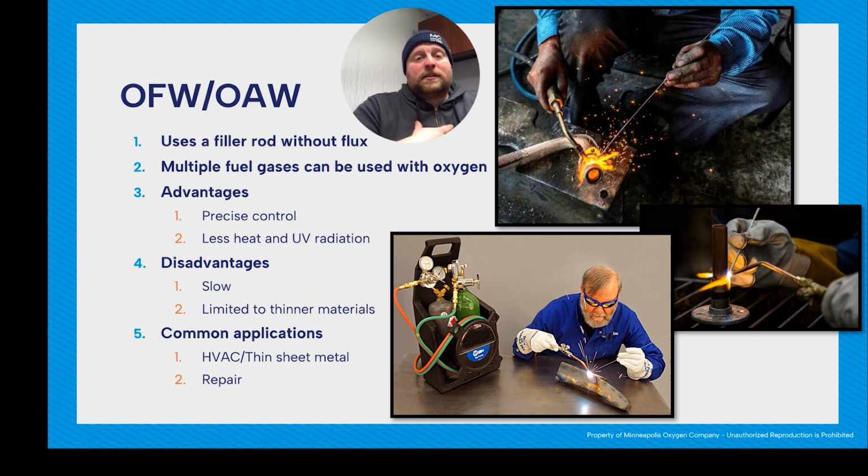I personally am a huge fan, if you have the opportunity, of oxy-fuel welding being one of the first processes you learn, because it allows you a very controlled, kind of quiet environment, I would say, to really learn what a weld puddle is, how to manipulate it, what your heat input does, things like that. And especially if you're going to go into TIG later, doing oxy-fuel is super, super helpful if you can do it.